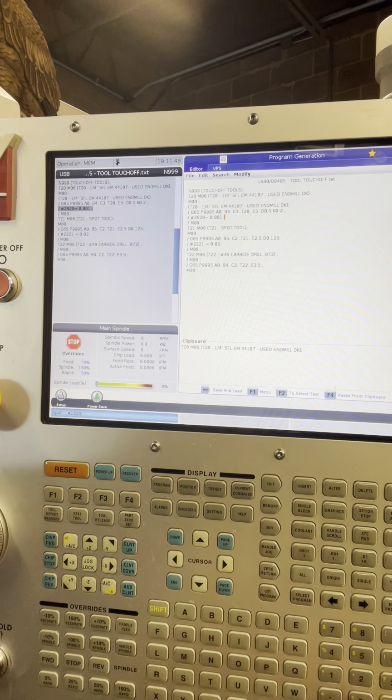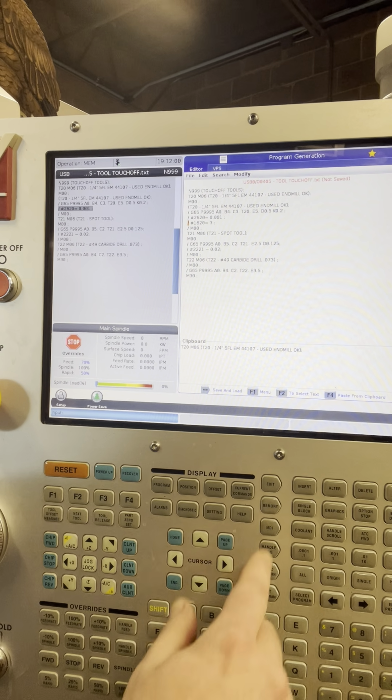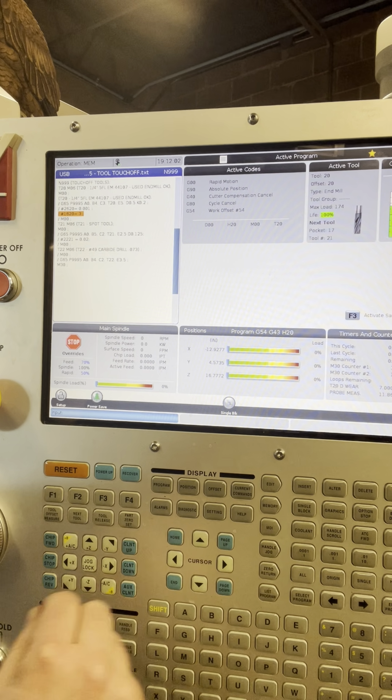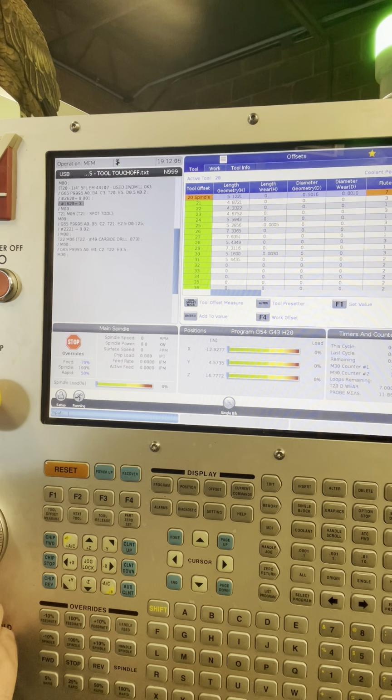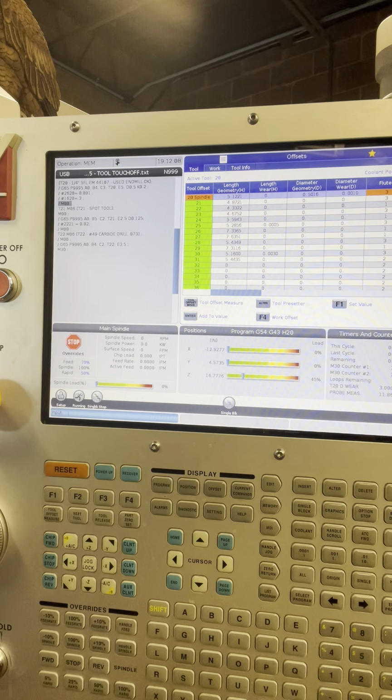So we're going to do 1620 equals 3 in the block. And I forgot to do the block skip again. Again, the block skip is just so you're not doing that when you're clearing out the tools. I'm just going to run single block on this one. So this one we should be able to see here. So you can see that changes that to 3.